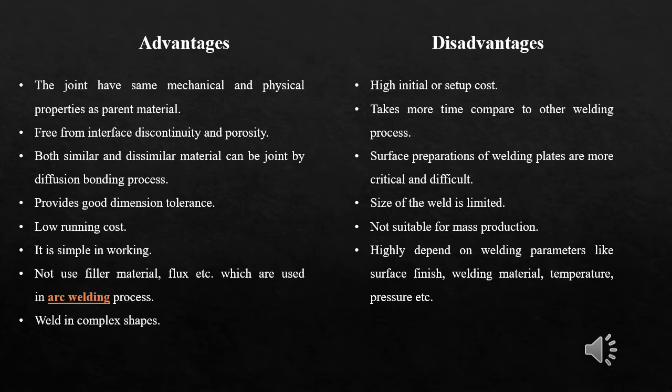The disadvantages itself are high initial cost, takes more time than the other welding processes, surface preparation of welding plates is more critical and difficult, size of the weld is limited, not suitable for mass production, highly dependent on welding parameters like surface finish, welding materials, temperature, and pressure.